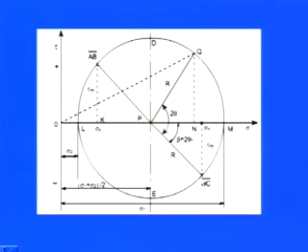So we have the BC bar, or we can say this BC bar is nothing but equal to, either you can take this is sigma x and tau xy. So you see here, pretty simple, the sigma x is this distance, and you see the tau xy of this distance. Similarly, you can plot also the AB bar, which is nothing but equal to this, the sigma y. So once you have the sigma y, you can also put the tau xy.